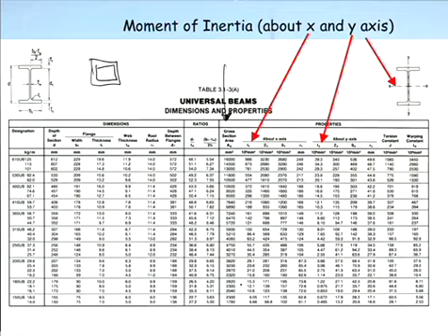So when you come and do your project design, once you've got your geometry sorted, your loading, you've done your method of joints, your method of sections, and you have a force, you're going to come into here and say, okay, here is my areas. Now, it doesn't say on here, but in your table, I think you're told it's C300 steel. It's either 300 or 350. When you see 300, that means your yield stress is 300. So look at your tables for your project and see what that number is,